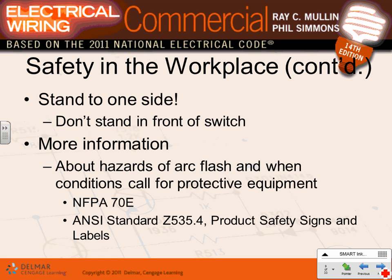This talks about standing to one side of the panel. If you're working on this panel, you're going to open it. If you stand right in front of it and there's an arc, what's going to happen? It's going to hit you right in the face, right? So stand to the side. You guys don't work on these.